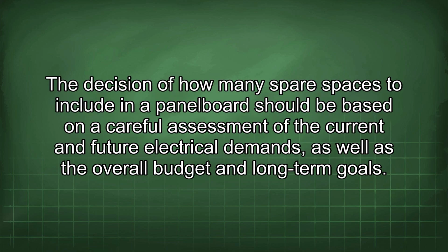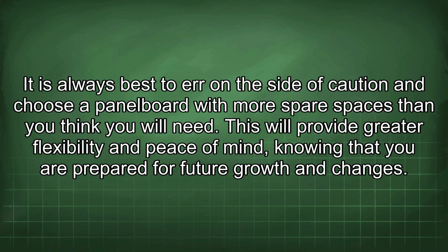The decision of how many spare spaces to include in a panel board should be based on a careful assessment of the current and future electrical demands, as well as the overall budget and long-term goals. It is always best to err on the side of caution and choose a panel board with more spare spaces than you think you will need.